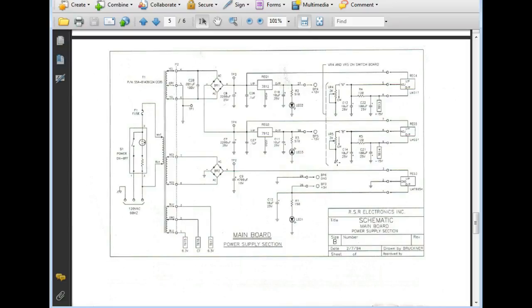So these are the power supplies on the trainer. This is a high current power supply. It's got its own. This is a 5 volt 5 amp regulator right here. And this is the guy that we're burning up left and right. It's actually a 78H05, and we're replacing them with another one that seems to be doing okay. So there they are. Very simple.